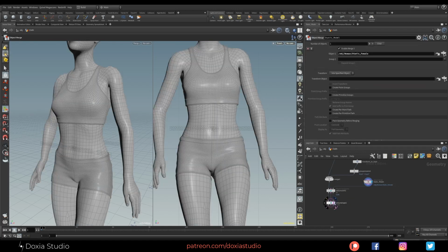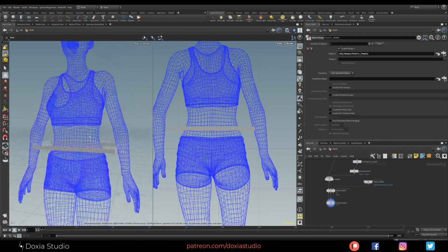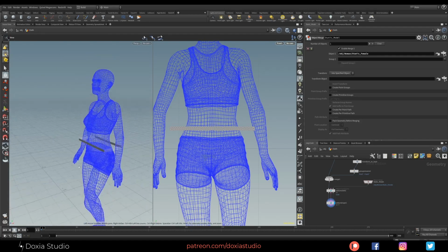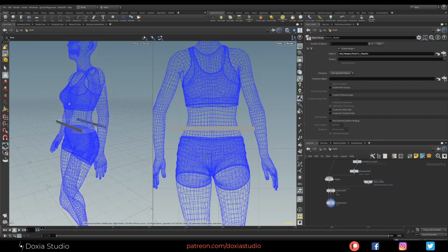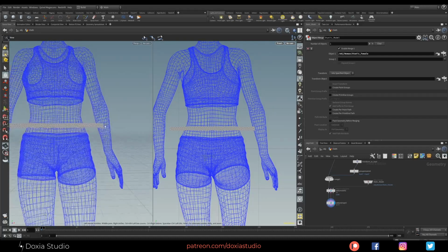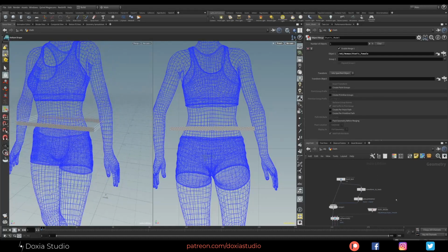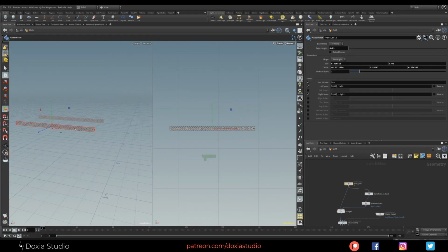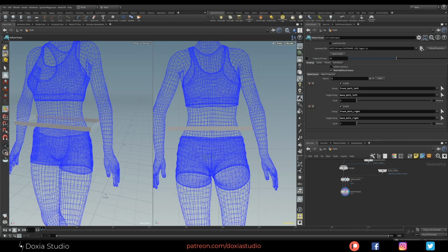Right now, if everything goes all right, we can see the collision mesh. Okay. So, one thing I can see is that our cloth is intersecting that arm. I think it's not a problem, but we can just move it a little bit to the side. Okay, let's stitch our belt. And as you can see, our belt is way too wide for the body, but it is behaving, and we stitch our cloth.